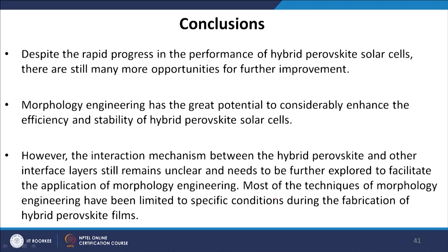So a very optimized exposure to water with the DMF solvent sometimes helps to improve the current and the fill factor. So in conclusion, despite the rapid progress in the performance of the hybrid perovskite solar cell, there are still more opportunities for further improvement of the device. Morphology engineering has great potential to considerably enhance the efficiency and stability of the hybrid perovskite solar cell. However, the interaction mechanism between the hybrid perovskite and other interfacial layers still remains unclear and needs to be further explored to facilitate the application of morphology engineering.